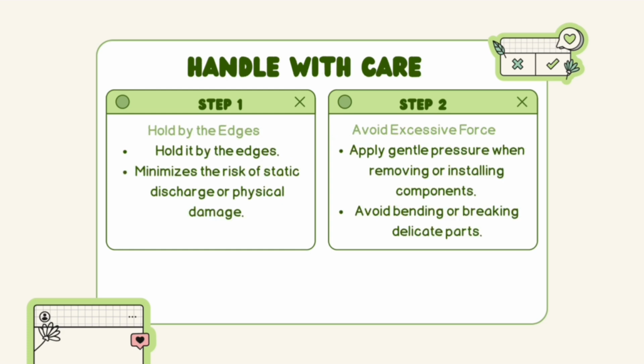Lastly, handle with care. Hold the motherboard by the edge to avoid touching the circuit board or components directly. This minimizes the risk of static discharge or physical damage. Avoid excessive force. Apply gentle pressure when removing or installing components to avoid bending or breaking delicate parts.